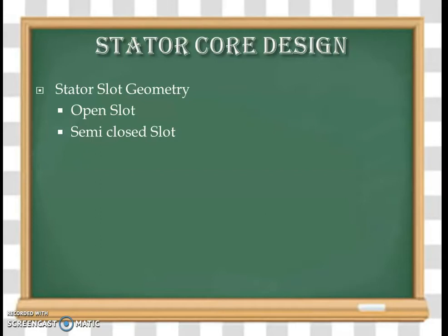The main advantage of semi-closed slot is a less air gap contraction factor, hence a reduced magnetizing current and improved power factor. At the same time, tooth pulsation losses are reduced and operation is with very less noise.